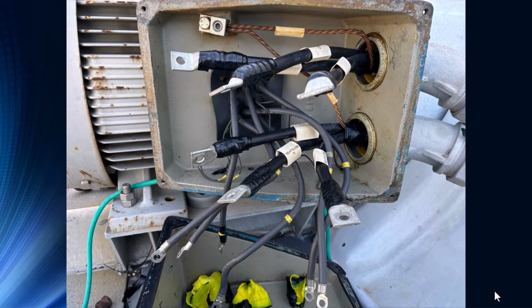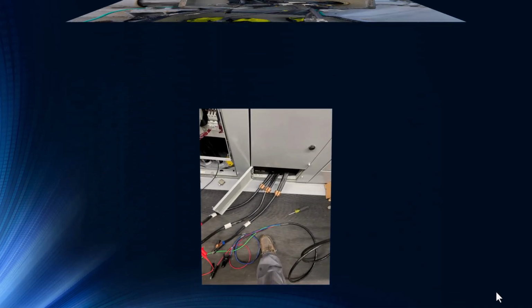Yeah, and here's at the actual starter itself, we have all the different cabling there. Right, 6 leads, and what do you want to do with them? Well, this is where the delta connection will occur. We could form this delta connection here, and then the dual cables that are traveling 1,400 feet can just be a parallel lead, leading to each phase. Right, which is what it looked like here.